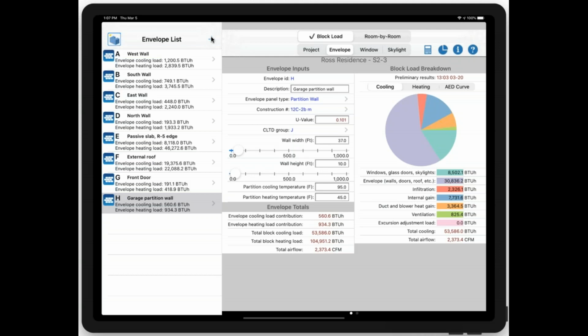Yeah. Well, is your basement conditioned? Did you say, or not? It's probably going to end up conditioned, so I should calculate it that way. Yeah. So if your basement is conditioned, then I would ignore the floor in between your first floor and your basement. However, obviously, the floor of your basement, you'll need to take into account for heating purposes.